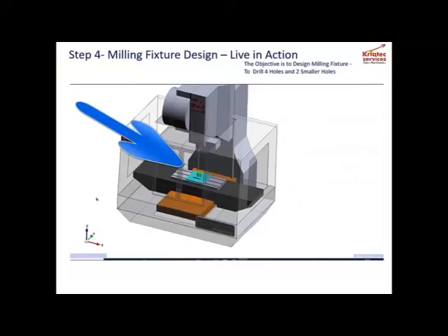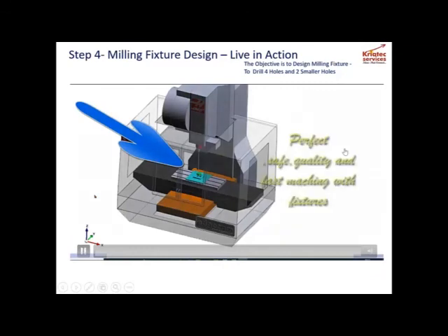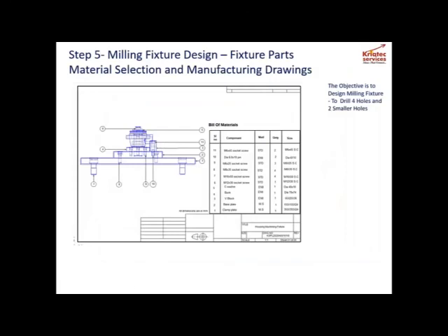What is very important, the big challenge in industry, sorry, let me put forward, is the manufacturing detail drawing. The basic mindset of people is that manufacturing drawing is easy. No. Even in my own experience, I can do the model in 2 days, but for the detailed drawing we take 4 days, though you can still do it a little quicker. What is very important is that people many times miss things. Similarly, you can add the datums here. The assembly drawing is very, very important. Bill of material is very, very important.